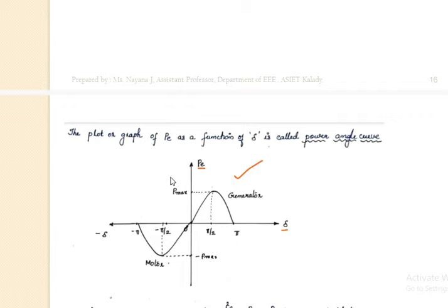Okay, so in this lecture video we have mainly discussed the concept of stability of a power system, and the different types of stability: steady state stability, dynamic stability, and transient stability. Then we have seen the mechanics of angular motion, that is, how you represent kinetic energy and moment of inertia, M is equal to H divided by pi f, or 180 into f.